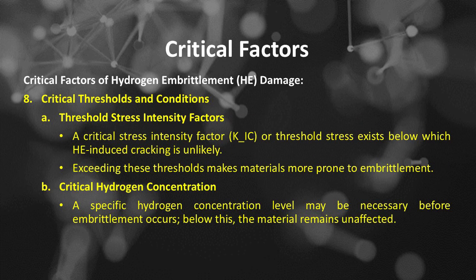Critical factors of hydrogen embrittlement damage. Number 8 is critical thresholds and conditions, includes, number A, threshold stress intensity factors. A critical stress intensity factor or threshold stress exists below which HE-induced cracking is unlikely. Exceeding these thresholds makes materials more prone to embrittlement.